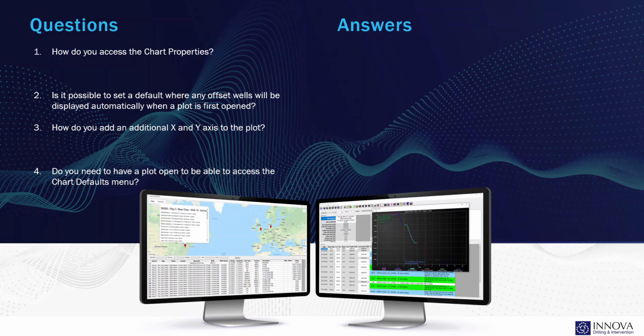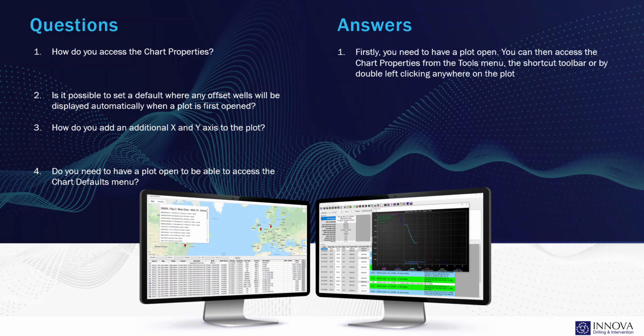So question number 1. How do you access the chart properties? So firstly, you need to have a plot open, and then you can access the chart properties from either the Tools menu, the shortcut toolbar, or by double left clicking anywhere on the plot.